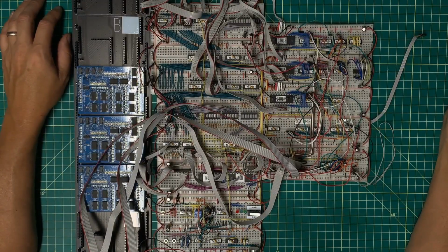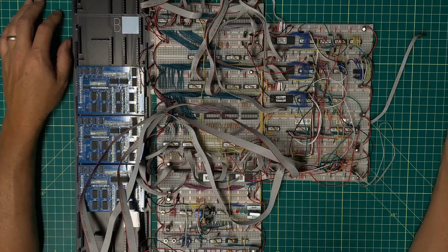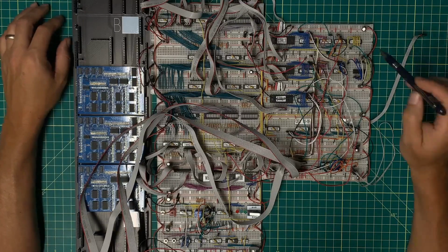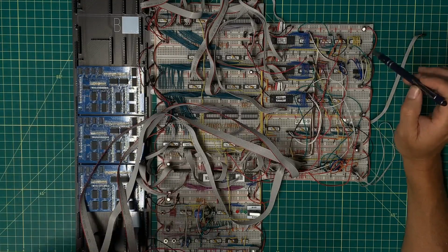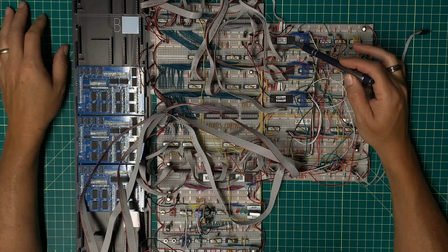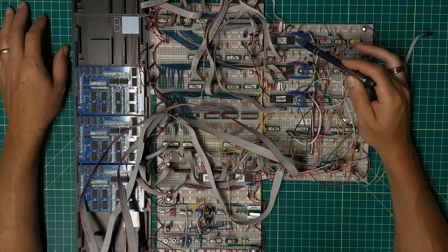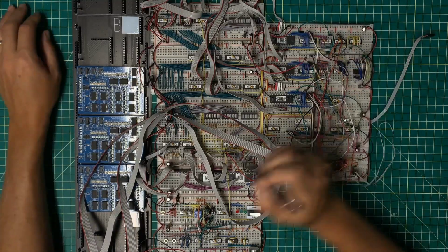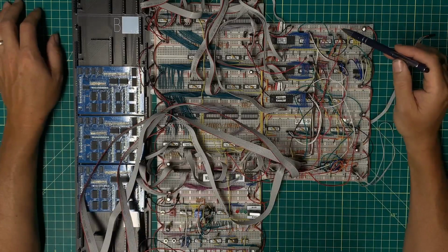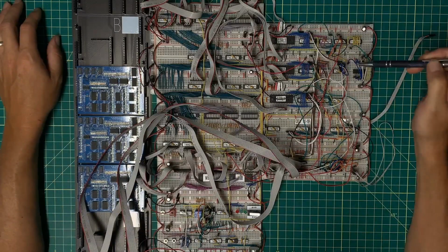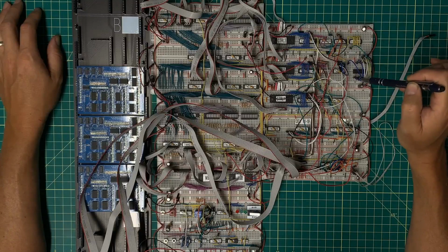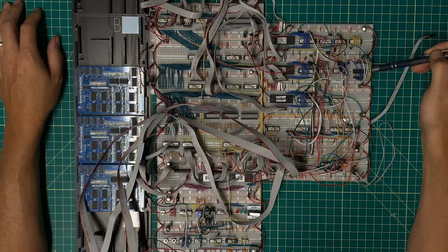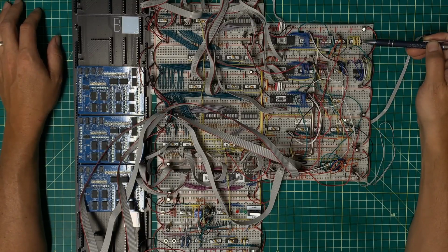Okay, let's start on zeroing in on the two sections of this build that cause me a concern, where I've added large-scale delays into the circuit. The first is up here in this corner. Now this is related to control ROM 3, which controls the AND latch signals. And in that I have managed to delay the clock by 12 inverters between this IC and this IC.